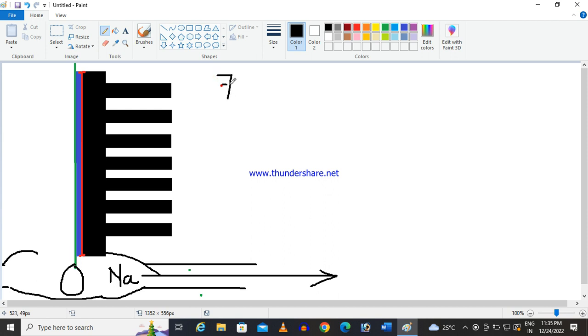The control valve leakage class is given by the FCI 70.2 standard. There the valve leakage is broadly classified into two categories. One is called seat leakage: once the valve is completely closed, some liquid may pass through when the disc is placed on the seat of the valve.